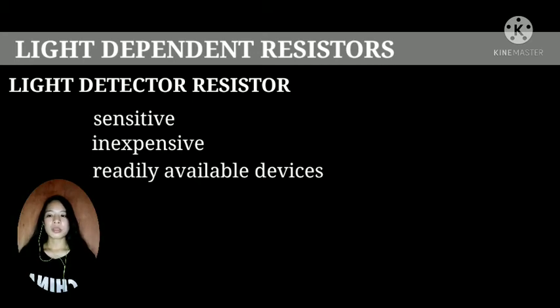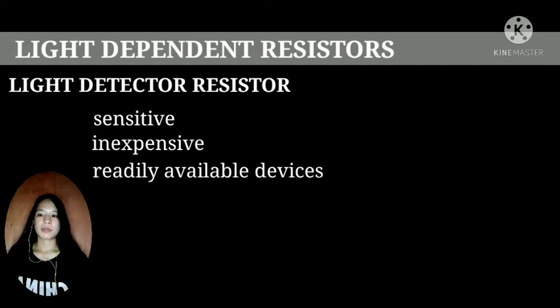They also have good power and voltage handling capabilities, so it is similar to other conventional resistors. However, the only significant drawback is that it is fairly slow in acting, taking tens or hundreds of milliseconds to respond to sudden changes in light level.